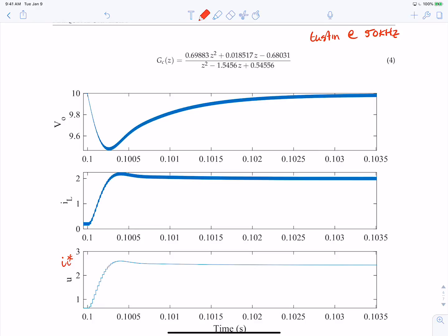So you really gotta take a look at these controllers and look at them after you convert them to the digital domain, both in simulation and in practice, experimentally, to make sure that you've retained stability from continuous time to digital time. And this gets even more exacerbated if you go to really cheap controllers where you may only have 16 bits, for instance, to represent all these numbers, and then it becomes a lot more challenging to design these because quantization kicks in, and that can make you unstable in a very big hurry.